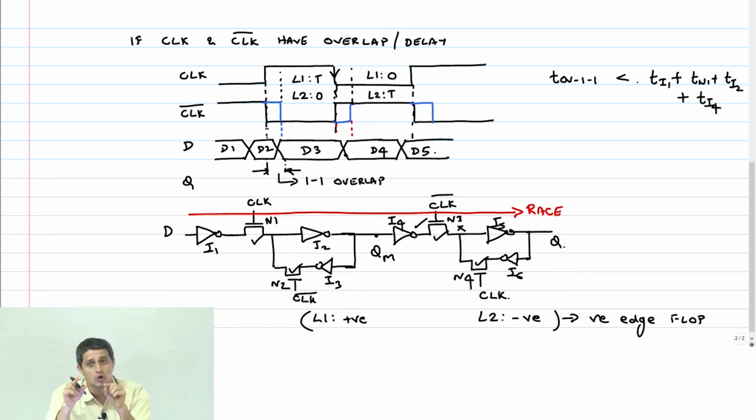So it is your job as a designer to ensure that there is sufficient delay from the input to the output so that you don't have this race condition. Okay.